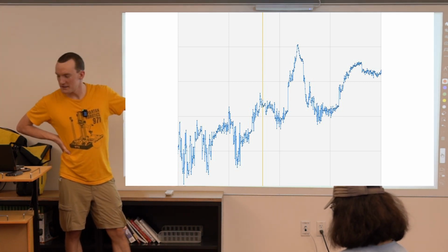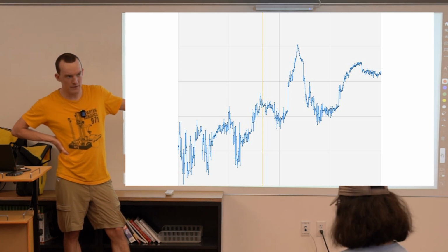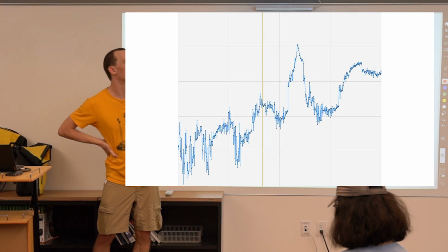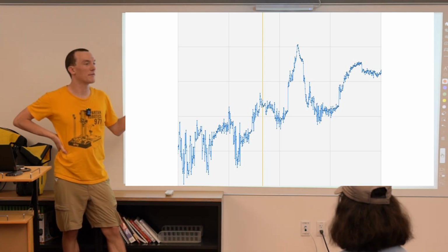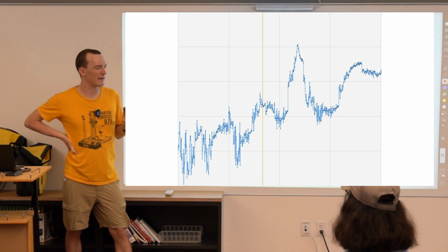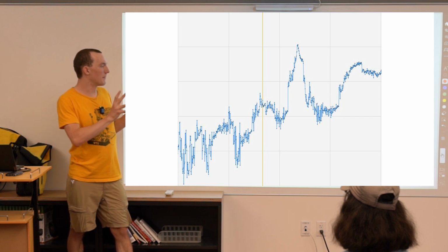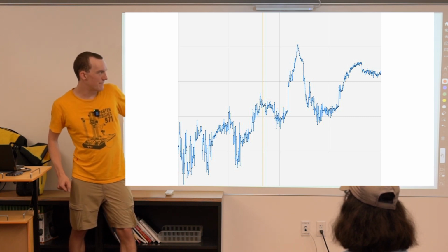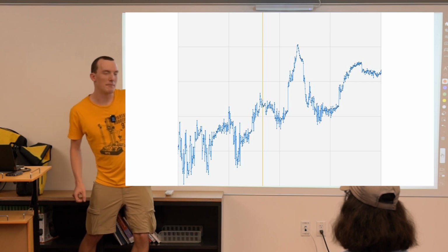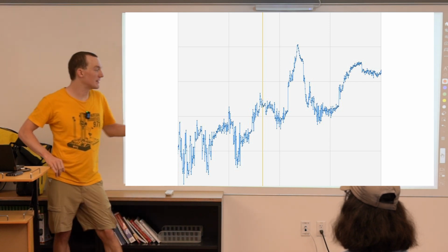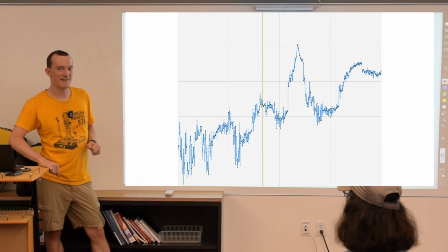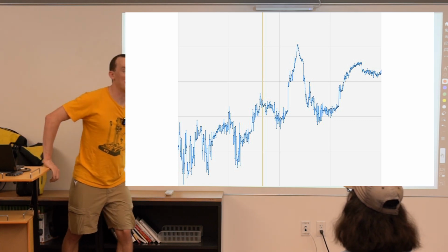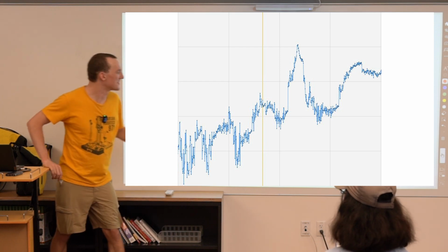This line is what happens if you take the speed number that comes directly out of the WPILib, or to be more precise, directly out of the RoboRio FPGA, I believe, the speed number for an encoder. Does this look like what the mechanism is likely to be really doing on a robot? Yeah, it really shouldn't be. And now, who knows? Maybe it really is, but it's not. I promise you, it's not.